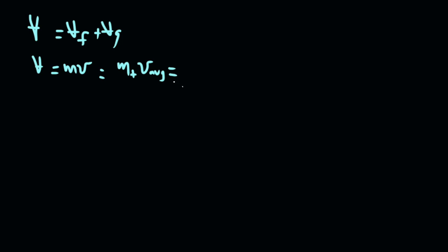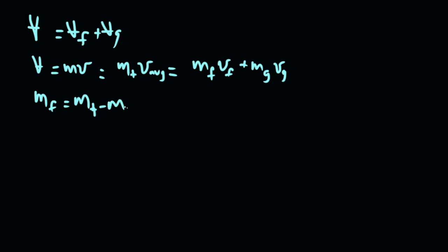And then the total mass is broken into two components. There's the liquid, so the mass of the liquid times the specific volume of the saturated liquid, plus the mass of the vapor times the specific volume of the vapor. That represents the total mass times the specific volume. If we want the mass of the liquid, we get the total mass and from it subtract the mass of the vapor.